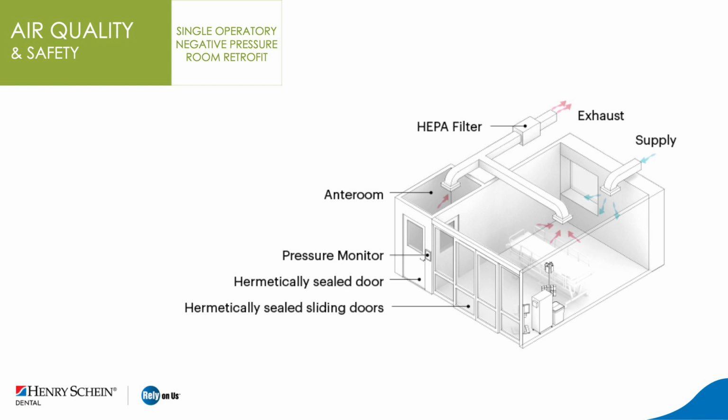And the percentage of fresh air is dependent upon building code in your particular locale. It could be a national building code specific and peculiar to health environments. So there's a ventilation component that has to be mixed with the recirculated air.